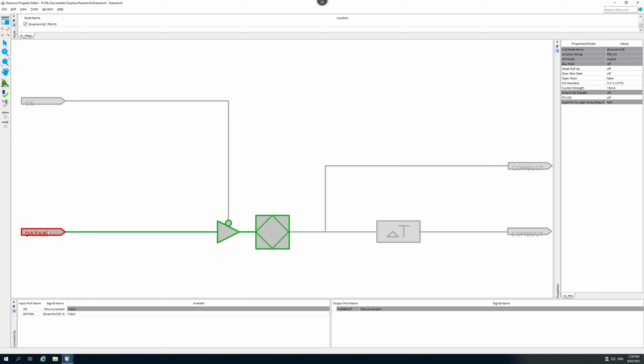If we have a look here, it's named capital E in our Verilog code. It goes through a buffer and out through the pin there. We can read off the same information down here. Pin E is what's going to be sent to the pin. Up over here, we see that the input-output mode is indeed in output mode.